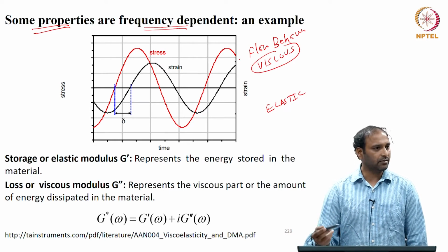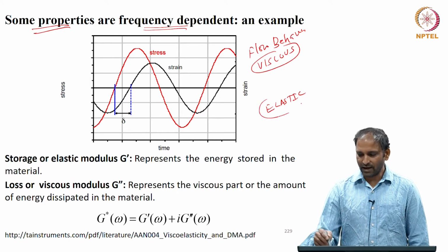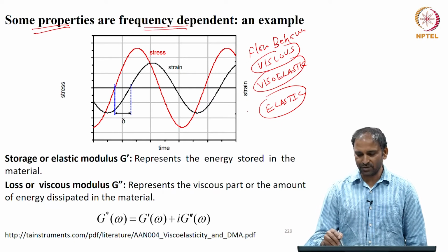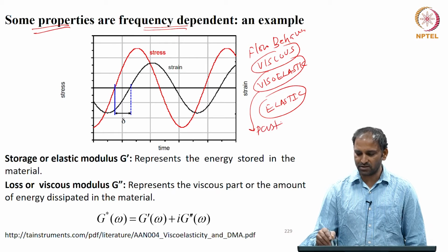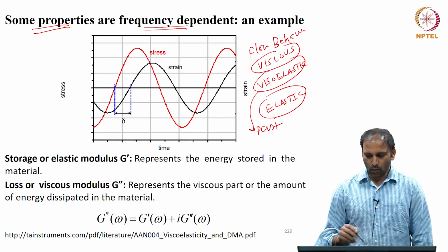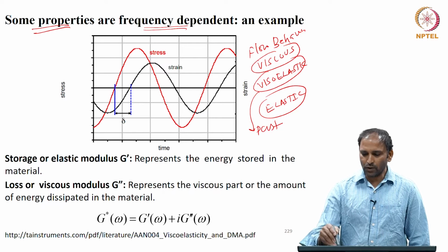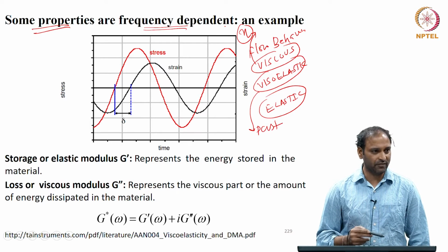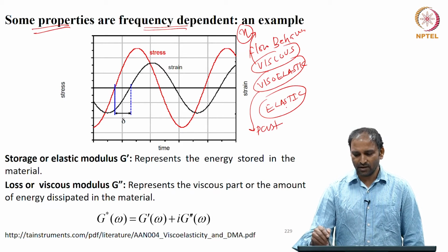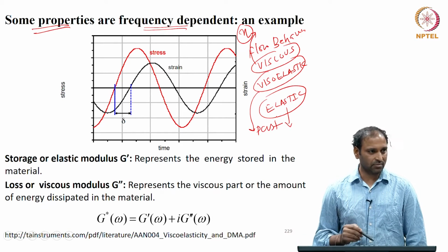These are more liquid-like, simple fluids that you can think of. Elastic materials are solids, but there are materials which are in between. They are what are called viscoelastic. One of the common examples of such a material could be something like a paste, for example toothpaste that people use, or ointment and things like that. Now, for viscous materials, you can use a property called viscosity to characterize its flow behavior. If one works with solids, then you can talk about something called the elastic modulus.